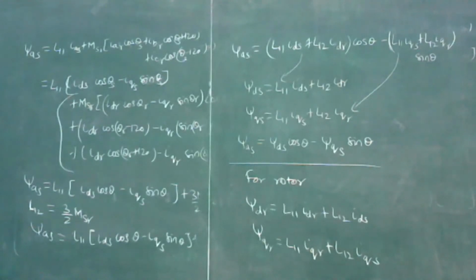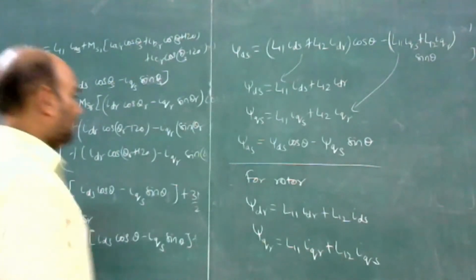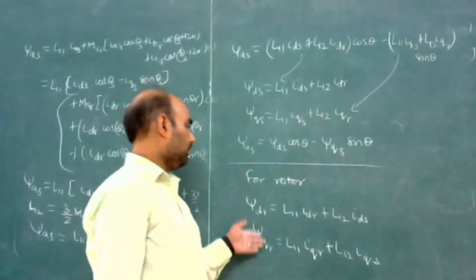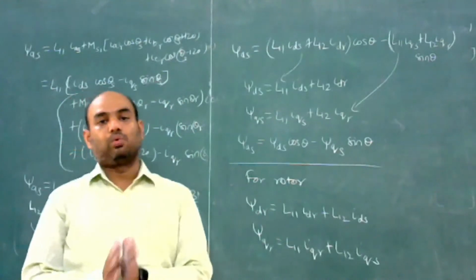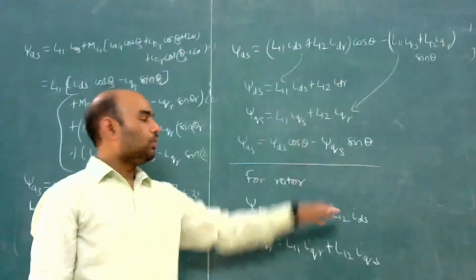Okay, so these are the flux linkage equations of the three-phase symmetrical induction motor using the dq rotors.